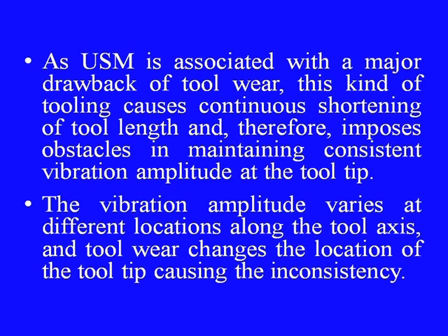As ultrasonic machining is associated with a major drawback of tool wear, this kind of tooling causes continuous shortening of tool length and therefore imposes obstacles in maintaining consistent vibration amplitude at the tool tip. So, this is a major problem as far as maintaining the vibration amplitude is concerned.